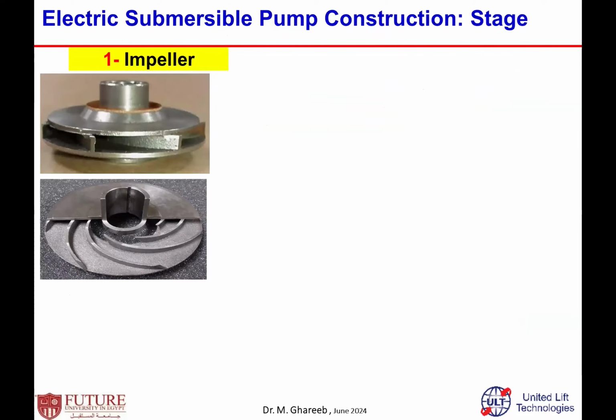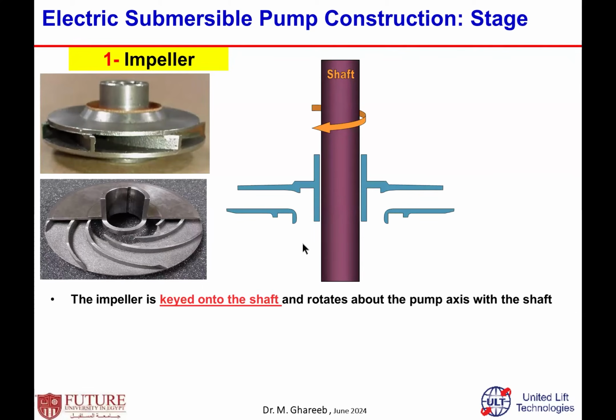Let us go a little deeper into impellers and diffusers, because this is a very important part. If I understand these parts, I will understand how the system runs, how to troubleshoot it, how to control it, and so on. As I said, the pump has different stages. Each stage has an impeller, a diffuser, and washers. This is the shape of the impeller, and the bottom one is a cutaway inside. This is the impeller of the stage of the pump.